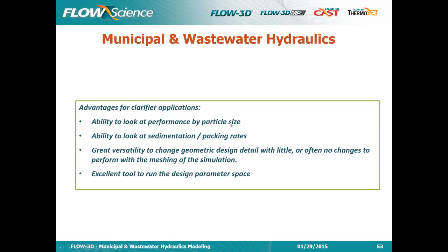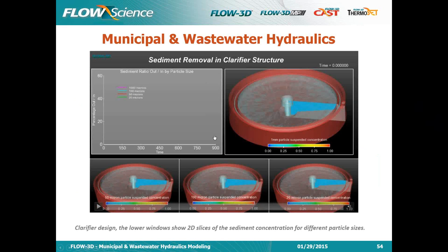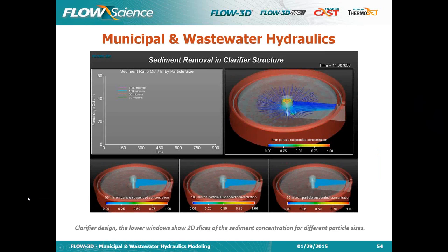You can look at things by particle size. You can look at things with how they pack and sediment, and there's plenty of versatility to change geometric design with usually no change in meshing because of the way we mesh things. So it's a really good tool to run, again, the design parameter space. Now in a sediment clarifier structure, finer particles.